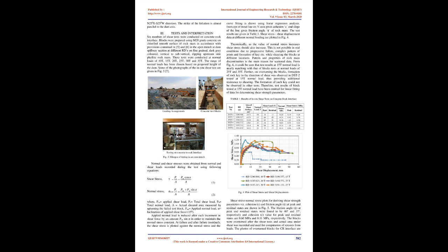At failure and after failure, residual, the shear stress is plotted against the normal stress and the curve fitting is drawn using linear regression analysis. Intercept of trend line on y-axis gives cohesion C and slope of the line gives friction angle of rock mass. The test results are given in Table 1. Shear stress, shear displacement data at different normal loading are plotted in Fig 4.